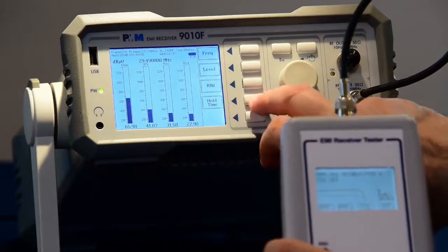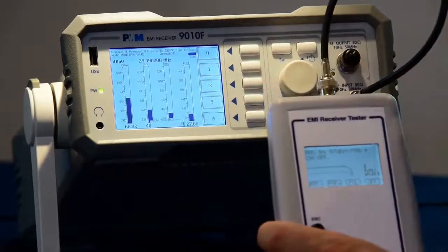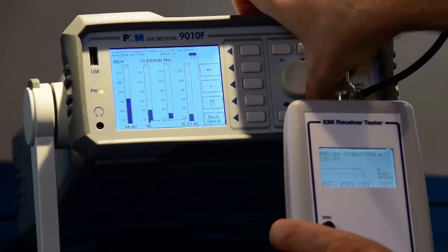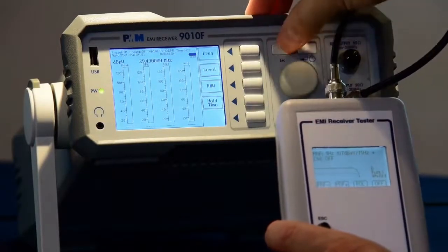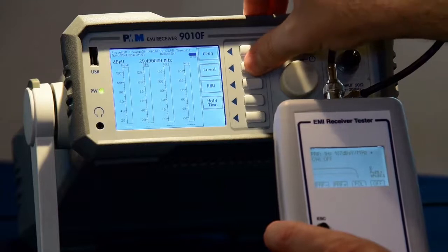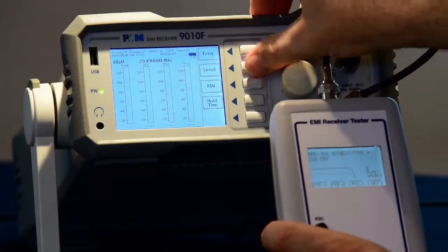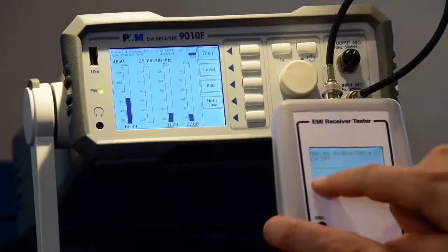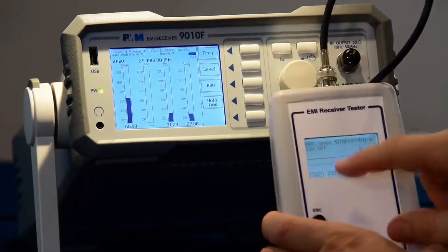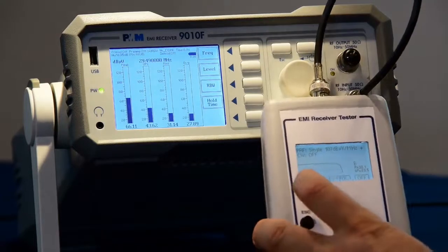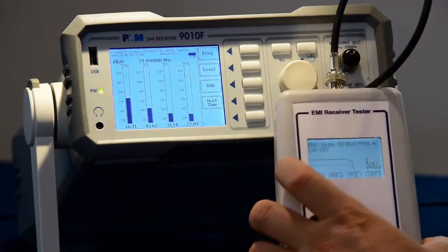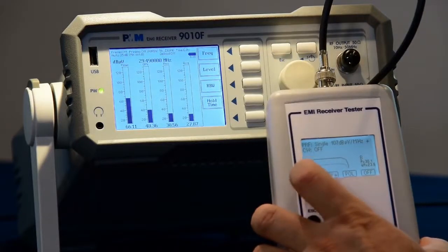So if we change the hold time and we set exactly 6 seconds, then we turn back again the selector, we can leave it off, then we will use also the on one. So we can apply the single pulse. For the single pulse we need to push the button and we will get it as soon as we are catching the signal.